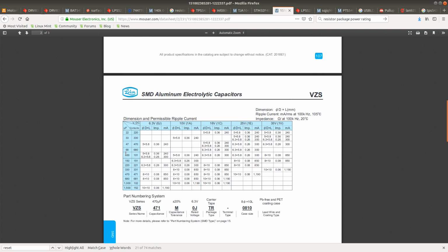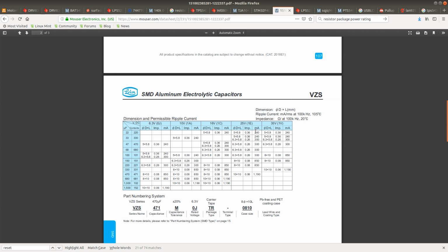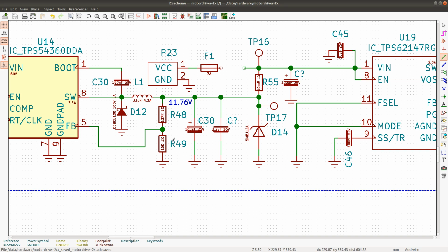So at 100 microfarads, 25 volts, it should support 300 milliamps, which is within the limit here now. That's good. Power dissipation of the diode is 2.68 watts, which is handled here because this is a 100 volt 5 amp diode.